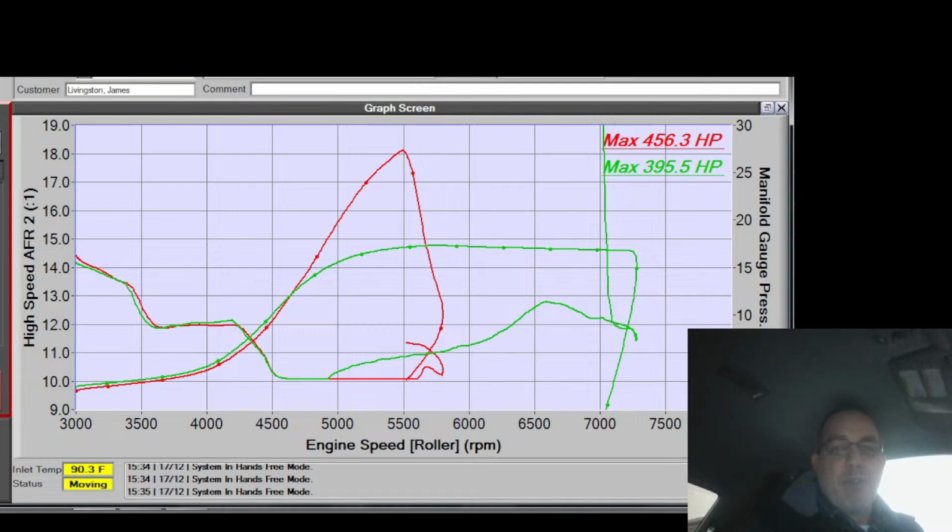That's actually kind of wonderful, because I'm looking at the fuel pressure and it wasn't lean from fuel pressure. That means that the VE on this smaller turbo is somehow better than the old turbo, which is way bigger, at this same level. That's crazy. That's great news, but that's crazy.